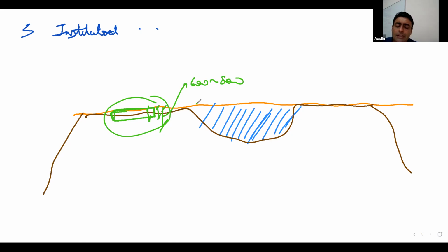Till now, they are facing this problem, that because they have disturbed the complete topography of this site, they always face the problems of water stagnation. They have not been able to provide proper service lines. So there is always a big problem. Their sewage system these days is not able to work on gravity, so they have to install pumps to pump their sewage to treatment plants. There are lots of issues, all because they decided not to respect their terrain.